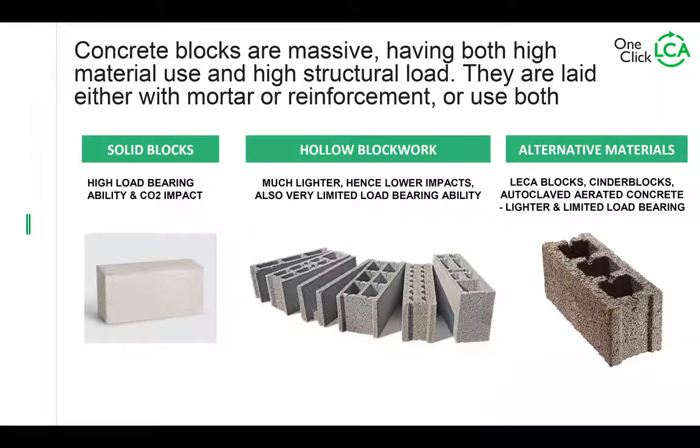And in some cases, they can be laid with kind of Lego-like bricks. That's a bit less common, but it exists, right? And solid blocks have high load-bearing ability and carbon impact as well. Hollow block work is much lighter, lower impact, very limited load-bearing ability, but it uses much less material. So in that sense, better.